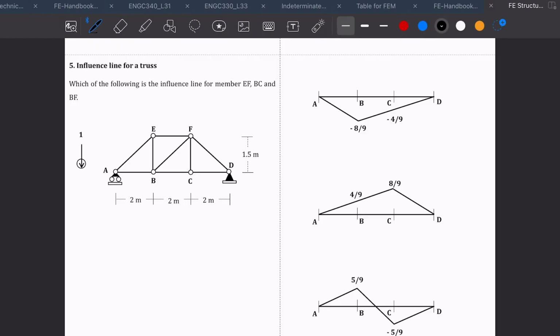You know that if this is a beam, and this is your roller support, and this is simply supported, and you're applying a load over here, we know that this beam will deflect. And if it deflects, we know that the top part will be in compression, and the bottom part will be in tension, which is positive, and compression will be negative.